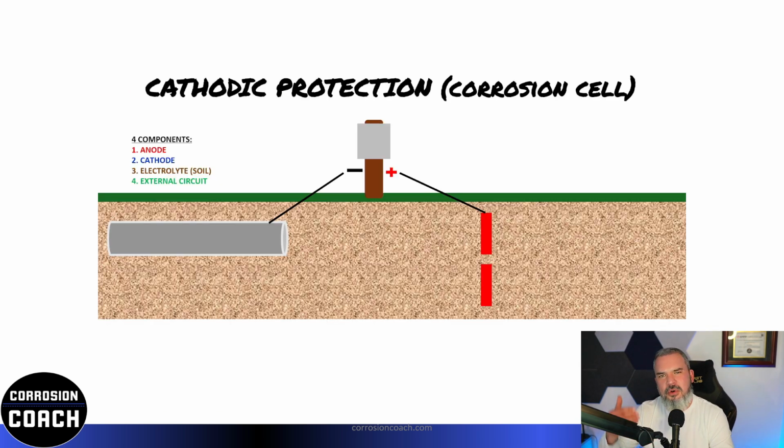You all know from probably the past or in one of my previous videos what cathodic protection is. What I'm showing you on this screen is we've buried our own anode material. We've attached it on the positive terminal of an energy source. In this case, it's a rectifier. And we're going to drive current off of those anodes, that sacrificial material, through the earth.